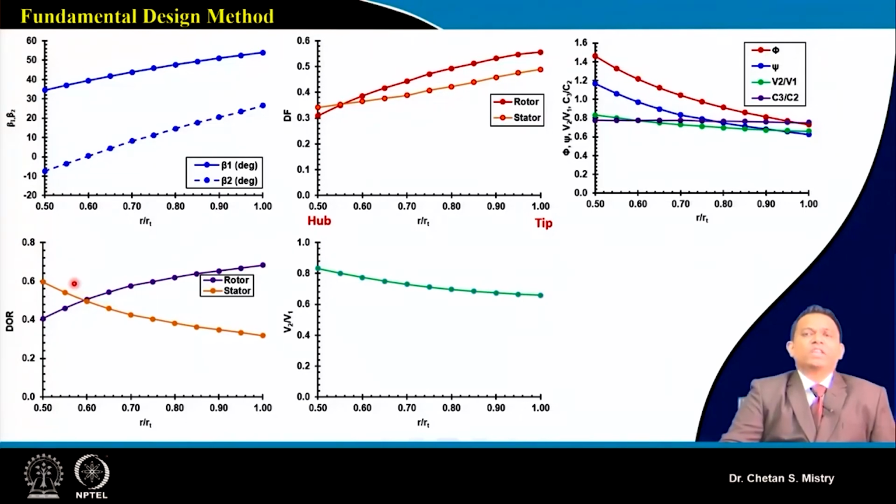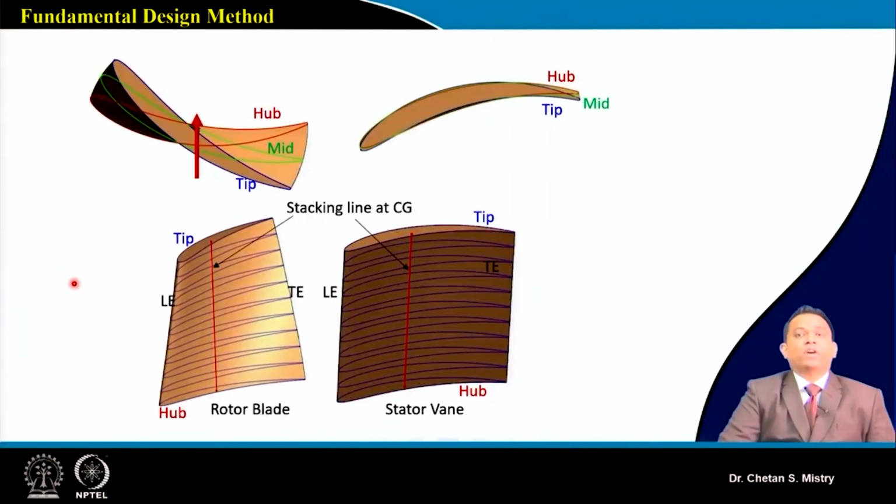Now this gives us the idea about the calculation of all flow angles, and based on that we can assume our aerofoil to be C4. We now understand calculating x and y coordinates for the aerofoil for the upper surface as well as the lower surface. Since we are using C4 aerofoil, we know the CG point, we know our stagger angle, and based on that we can do the calculation here. Okay, and we can generate our geometry.